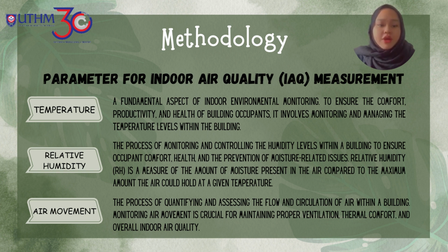Parameters for indoor air quality measurement. For temperature, a fundamental aspect of indoor environmental monitoring to ensure the comfort, productivity, and health of building occupants, it involves monitoring and managing the temperature levels within the building. For relative humidity, the process of monitoring and controlling the humidity levels within a building to ensure occupant comfort, health, and the prevention of moisture-related issues. Relative humidity is the measure of the amount of moisture present in the air compared to the maximum amount the air could hold at a given temperature.